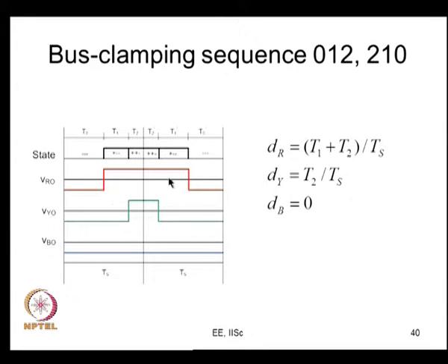Now, if you go here, the B phase is not switching. So, here what you have is only ER plus EY, and again ER is a function of IR, EY is a function of IY, and EB there is no loss at all. So, you save a certain amount of energy here, when you are looking at it on a sub cycle by sub cycle basis. So, it is only ER plus EY, where ER is the switching energy lost in R phase, and EY is the switching energy lost in Y phase.